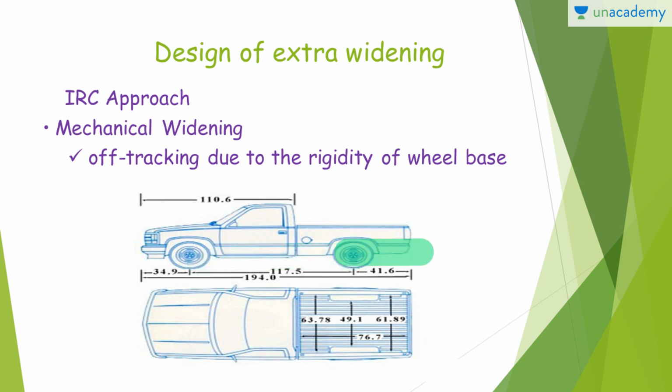As I told you in the previous video, the front wheels turn with the steering, but the rear wheels don't turn, they follow the straight path. So that leads to the off-tracking, and that is basically due to the rigidity of the wheelbase.